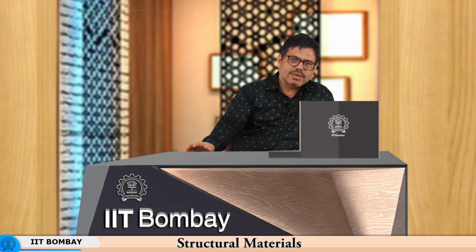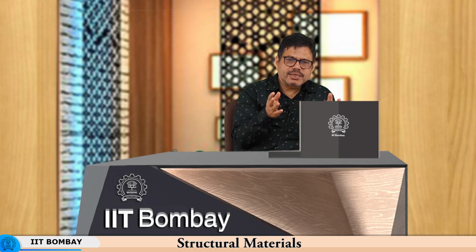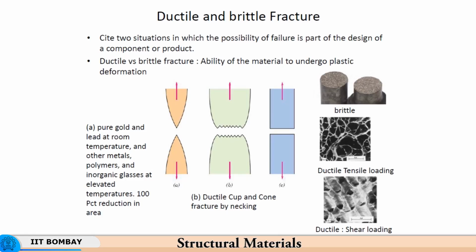In a brittle fracture, the failure occurs between two grains, whereas in a ductile fracture it is transgranular. That is because the deformation takes place inside the grains; the ductility of the material is due to deformation in the grains. So I am presuming that it is a room temperature deformation, or the deformation is taking place at a temperature below the so-called equicohesive temperature. So here the grain boundary is stronger than the interior of the grain.